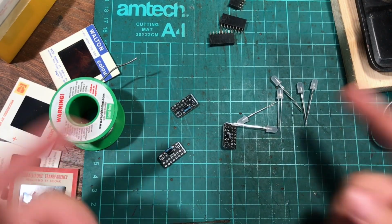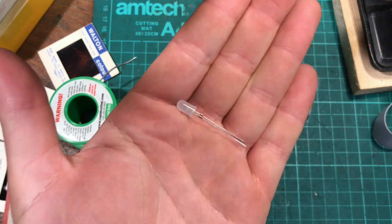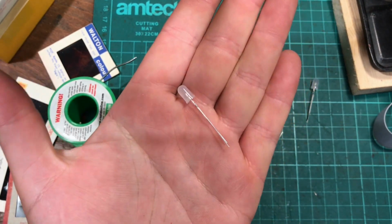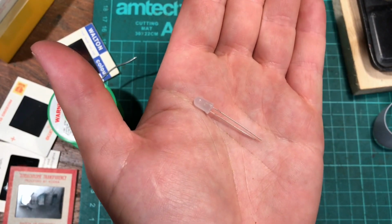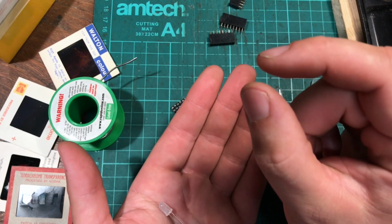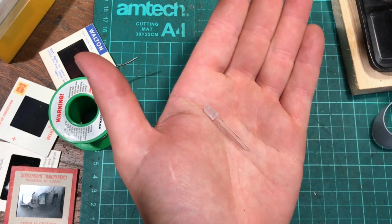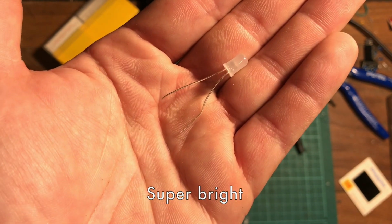Now we're going to solder in the LEDs. I'm using these ones here. They're 5mm diffused warm white, and you really need diffused LEDs for backlighting these panels to spread the light out so you don't just get a little spot of light on the back of the panel. The brighter the LEDs, the better, so try and get the ones that say super bright.